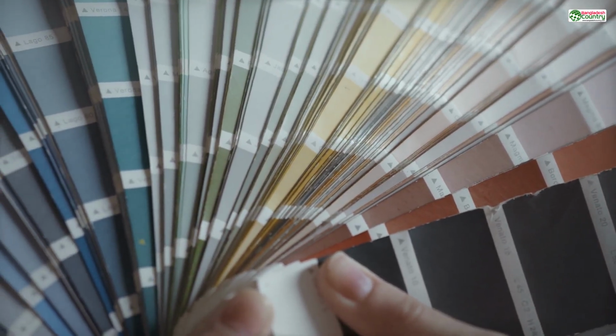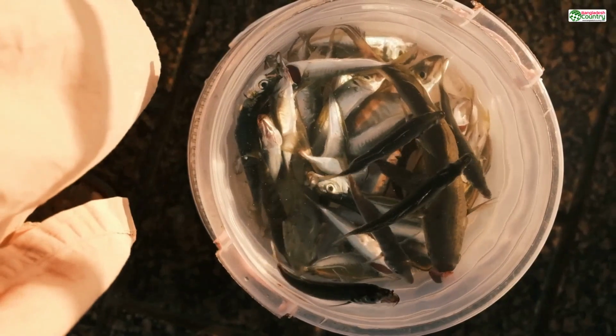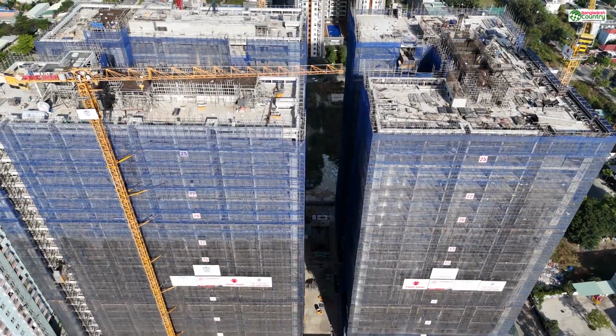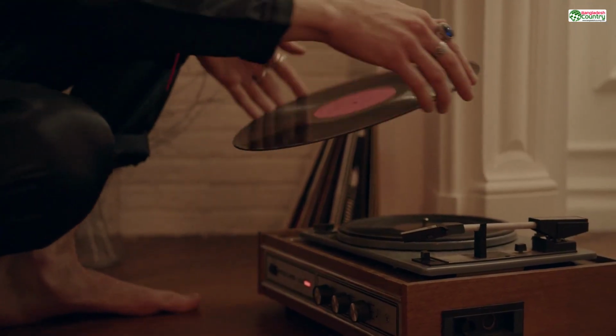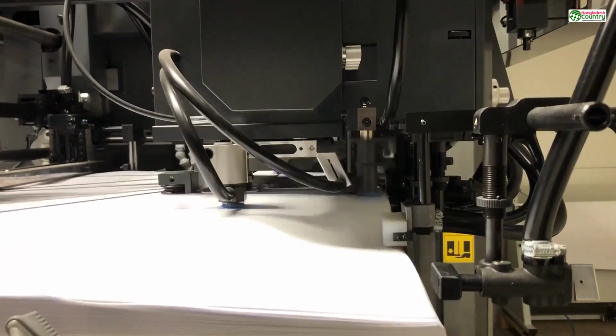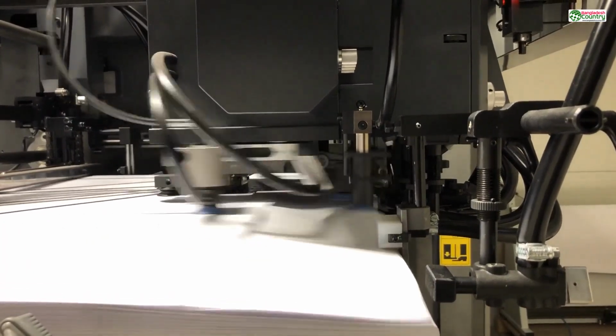But here's the catch. To build a 1-inch tall object with 0.1 millimeter layers, the printer has to draw 254 individual layers. That takes a lot of time. And when you're using an online service, time is money. A longer print time means the machine is occupied for longer, so the service has to charge you more. So low layer height equals high quality, but it also means high cost and a long wait.